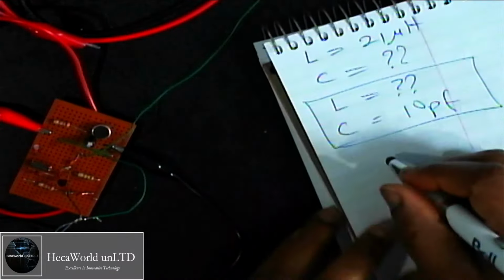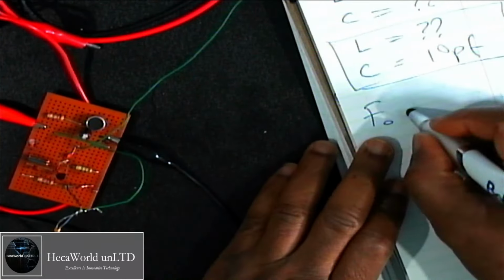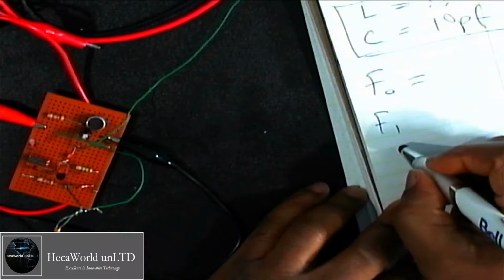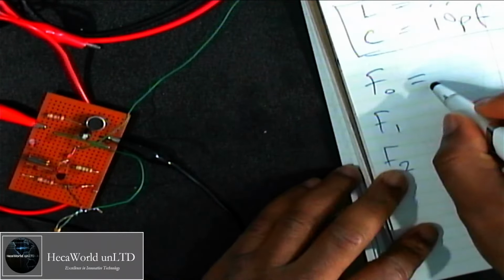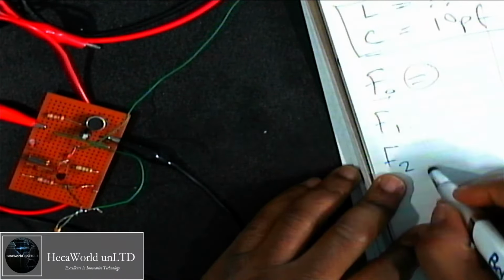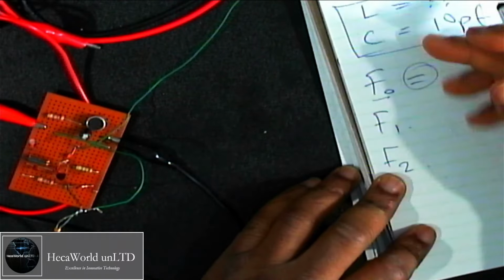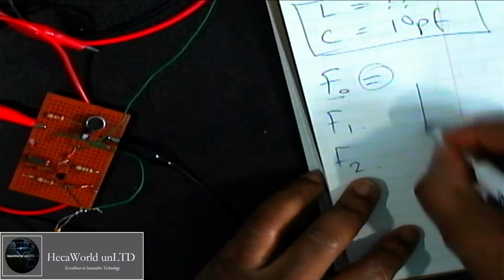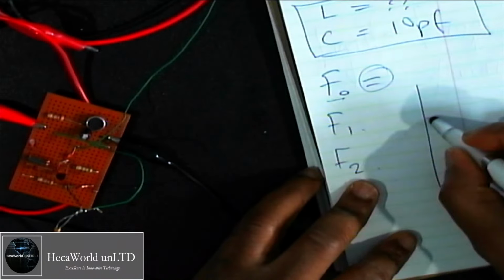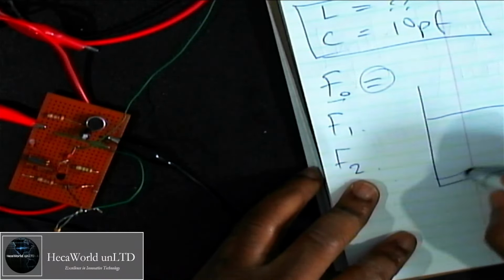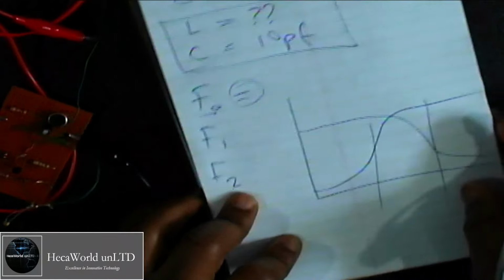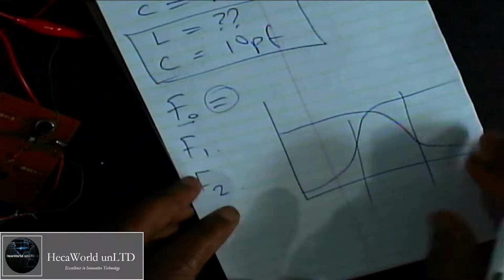Now remember I said F is the fundamental frequency, F0, so that means there's F1, there's F2. At every multiple of F0, you get another frequency, another signal being transmitted. So if you want to build this system, make sure you have a band pass filter, which will filter out lower frequencies. Let me show you that. Let me draw this so you see me drawing it.